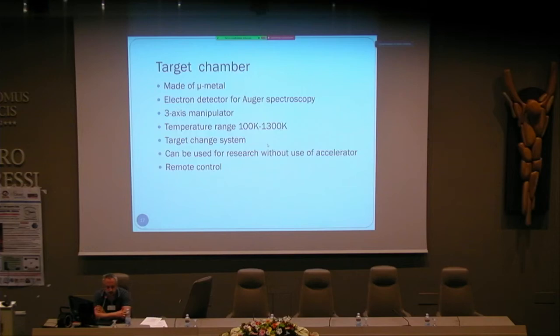As I said, we have a very sophisticated pumping system, and we have a so-called cold pot. This is a huge pot filled with liquid nitrogen, so it takes most of the water from the chamber and traps it in the liquid nitrogen. We also have a titanium pump that spreads titanium and binds the contamination in the chamber walls. So these are the main systems to get rid of the water.